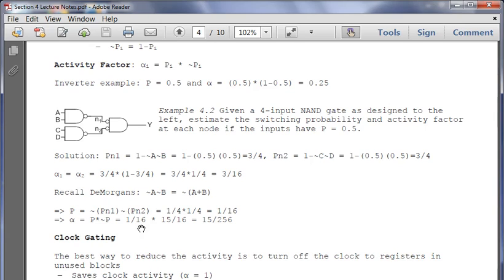Yeah, so you're doing activity factor. For this example, we're just ignoring the equation. We're trying to make it intuitively make sense. So that means this can actually go to 31 from that last 1, 1, 1, 1, 1. So this is going to become 31 times 32 squared. There you go, 31 over 1024. Now, do those numbers make sense?